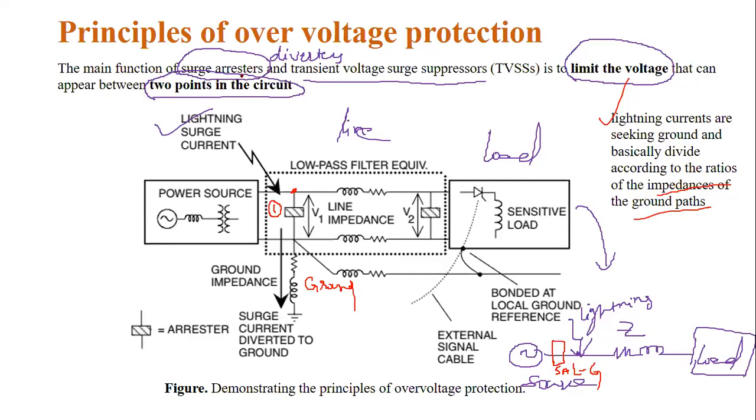What the surge arrestor or surge diverter does is it can divert a huge amount of such currents or lightning currents from any of the phases. Remember, any of the phases. Suppose it is a three-phase system: phase A, phase B, phase C, or whatever it may be, any of the phases, or you can also call it line to ground. Remember, not the neutral, the ground. This is the line. You can assume in the single line diagram, this is the line and this is the neutral.